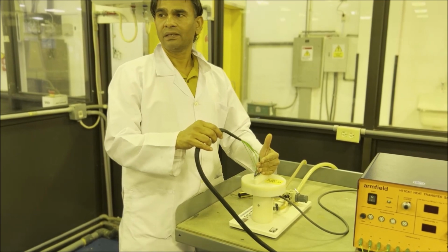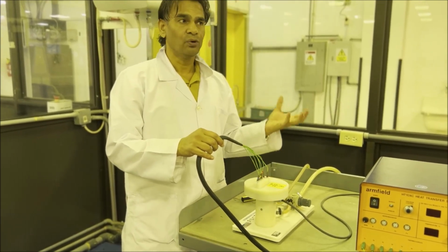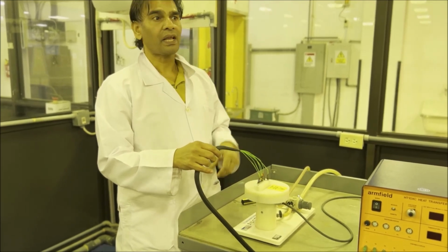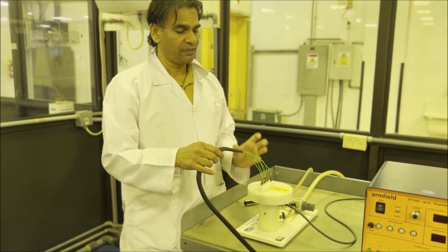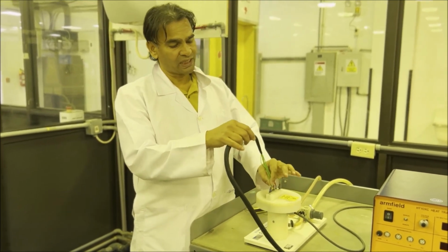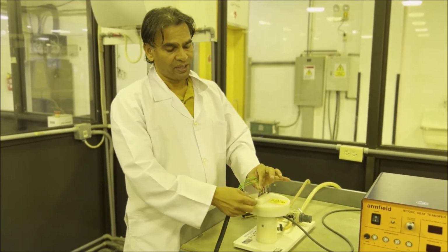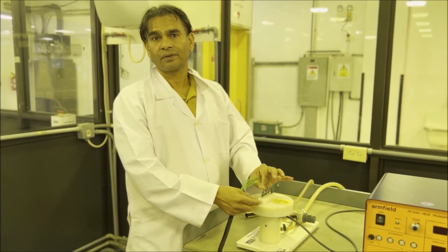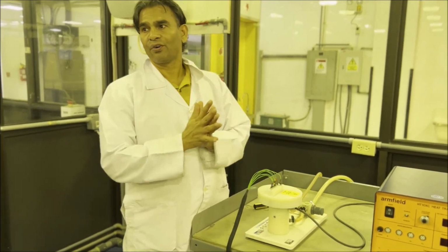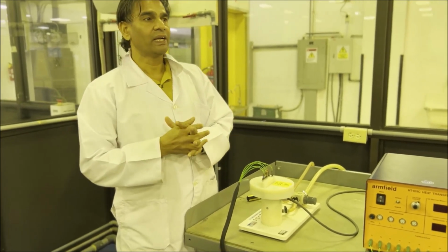If I know temperature, radius, Q and area, I can find out thermal conductivity. If I know temperature, Q and thermal conductivity, I can find out the outer temperature. Only one unknown. So our target is just write the formula, put in values and get the answer.